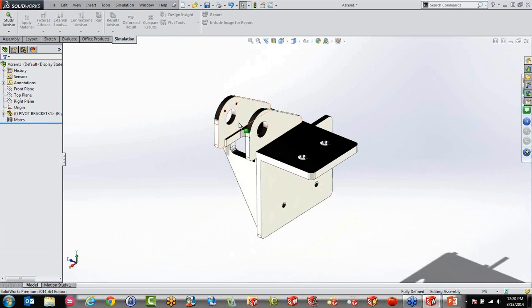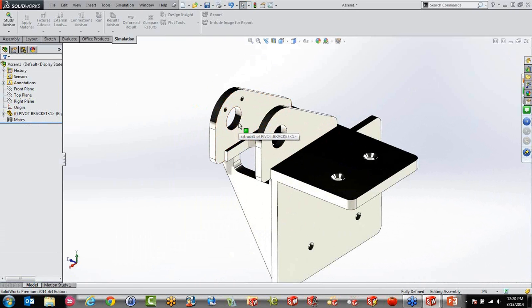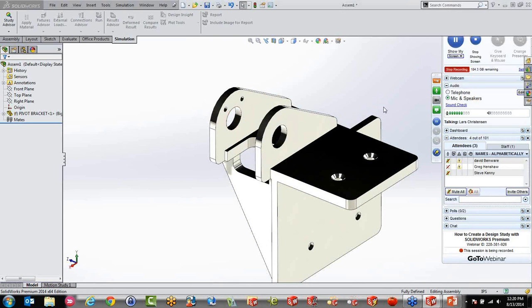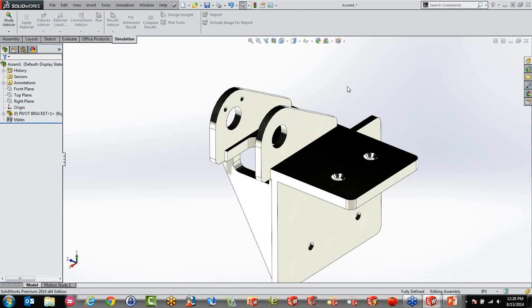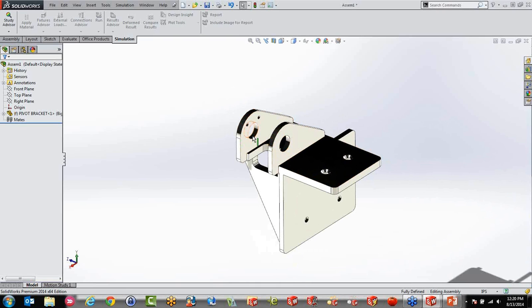And what is neat about doing FEA analysis right inside of this environment is that we can play around with different things. And since we're inside SolidWorks, it's very easy to work with things. So I might say, all right, I know that there's a rod going through these holes, it's going to pivot over, and that's maybe actually where the load's going to be. The load is not going to be just on that little area of the part. It's actually going to be out here.